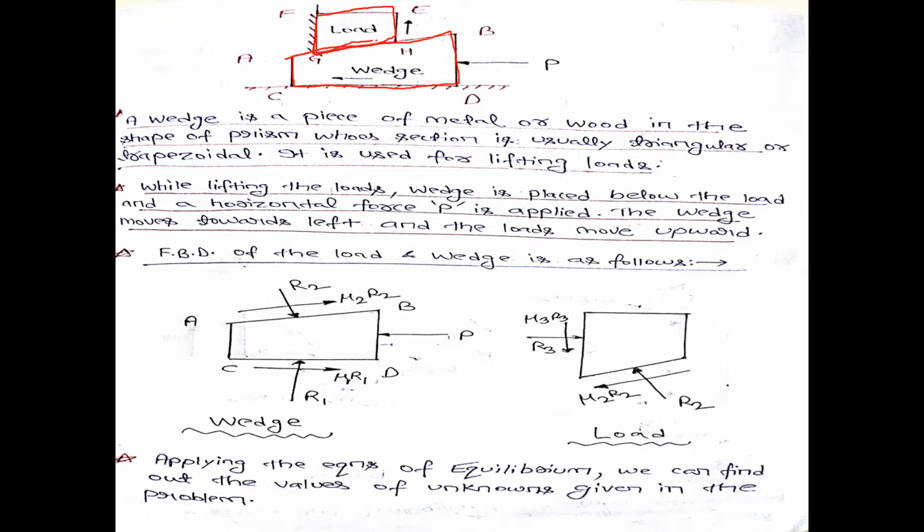How can you lift it? You have to take the help of the wedge. If on this wedge you apply a force P in the negative x direction, what will happen? The wedge will move in this direction. Since the load is in contact with the wedge, the load will move upward. Is it clear? Yes, sir.